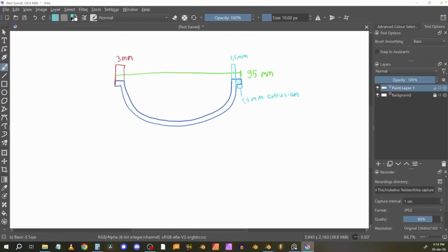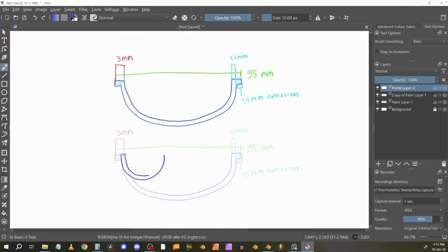So we really need to worry first about the ball shape itself. Now for the cylinder part, we basically have a cylinder like this, which is cut in half. So it's basically this shape. And I'm going to say it's also most likely the same thickness as the rest of the ball. So it's also 1.5 millimeters. But it also has this extruded part on the side. And together with the extrusion, that half cylinder is 32 millimeters wide. And the extrusion also goes all the way around the rim of the cylinder.